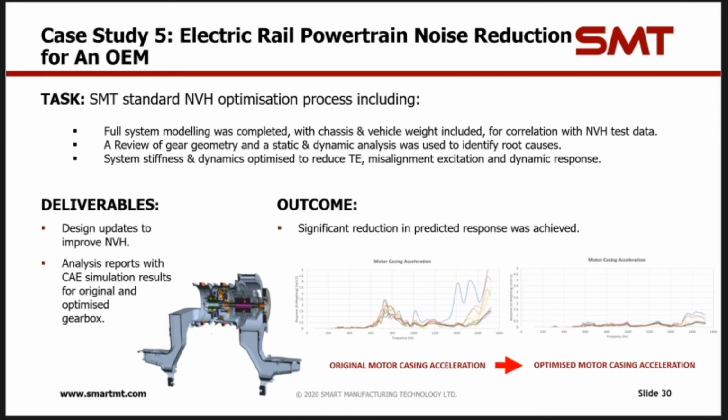And this was backed up with the client's pre-project experience, where they had tested helical gears and found that the overall response was worse. So we restricted to optimizing the gears to spur gears. So we went to high contact ratio gears on one of the stages.